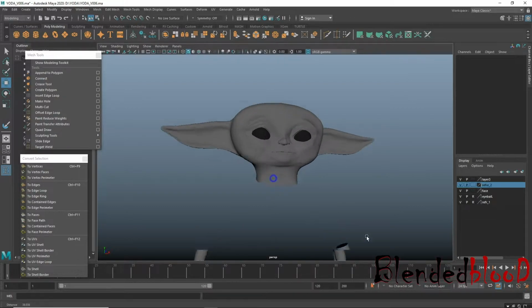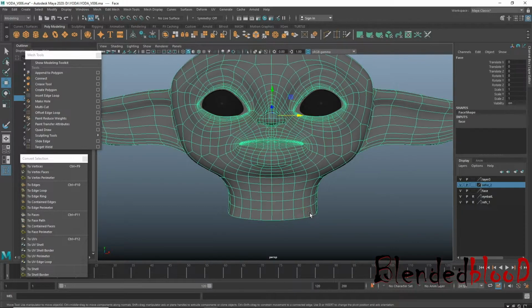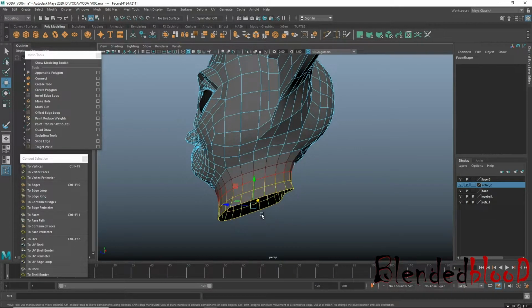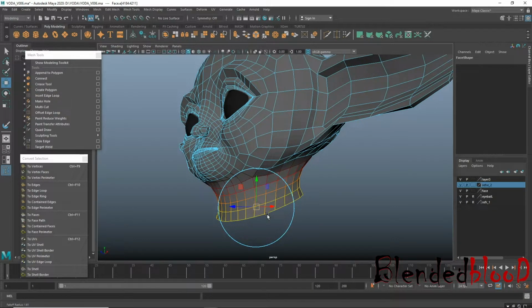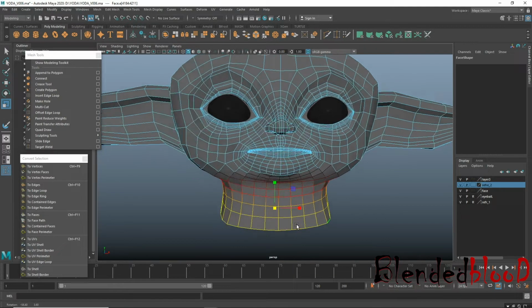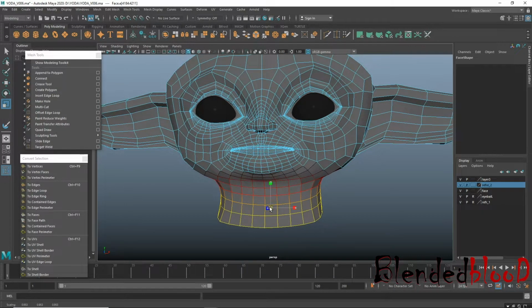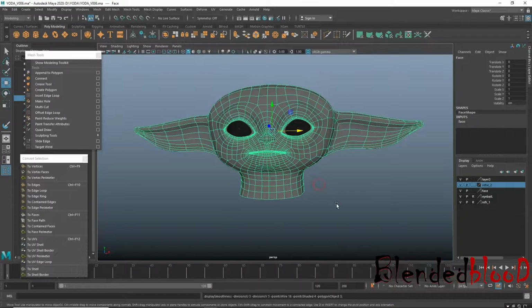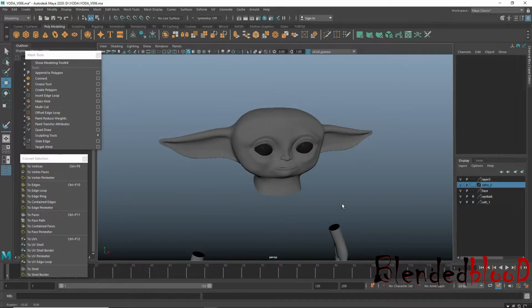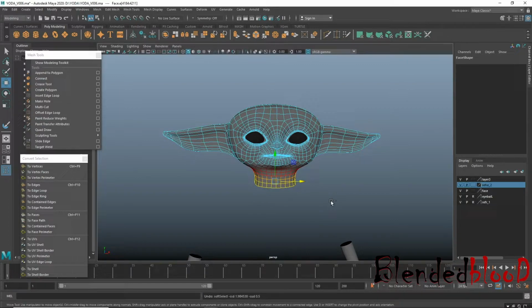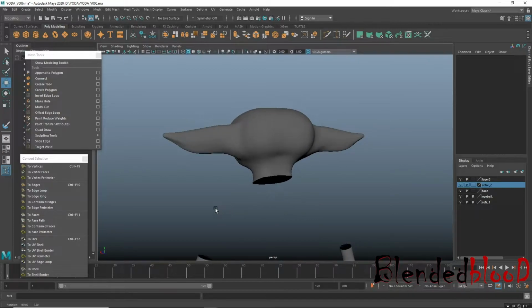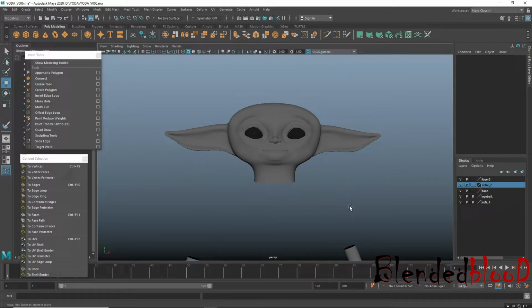Okay, now go to edge, press B for soft selection, increase the soft selection area, press R and scale like this. Okay, a bit less, B. Now you got your neck. Yeah, I will prefer this one, because after increasing, that was looking kind of weird, very much weird.